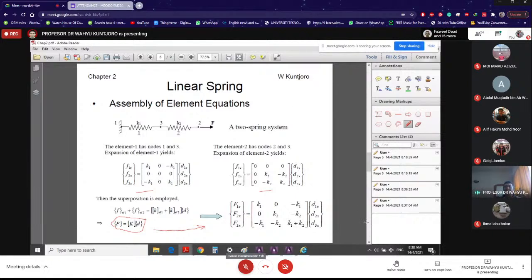So now, by doing this, then we understand how we do. Number one, you understand your problem. Number two, you know what element type to select. Number three, you understand meshing. Mathematically, when you do meshing, this is actually what you do. You construct your structural equation, the assembly of the equations. Once you have this, then you will do what we call as introduction of boundary condition.